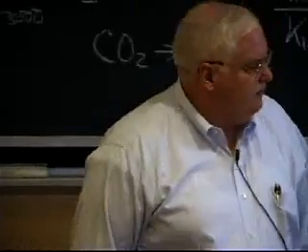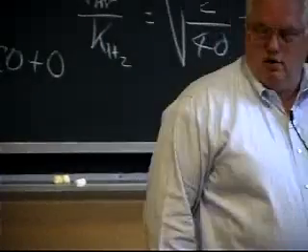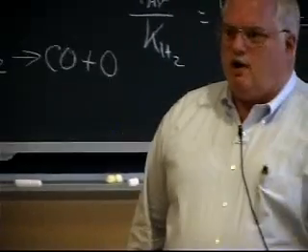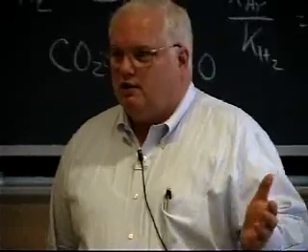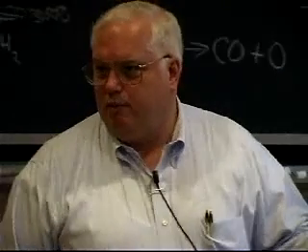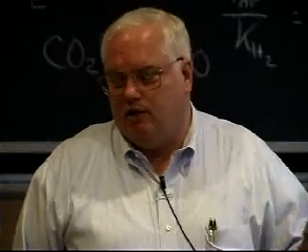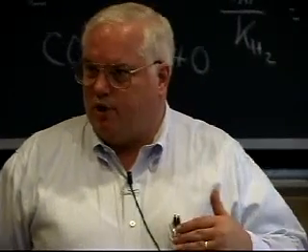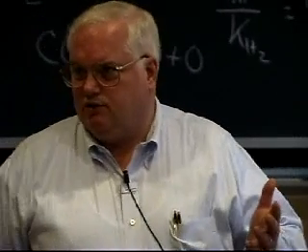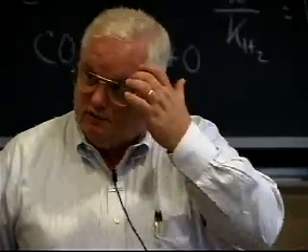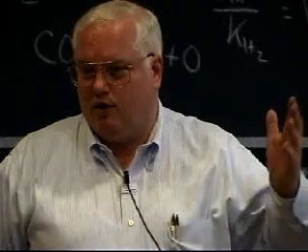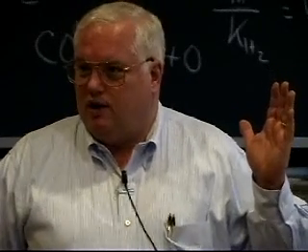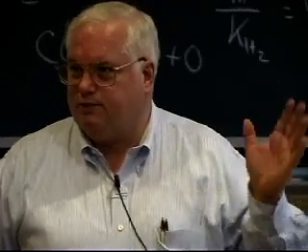Your total burdened cost to have a person welding and everything is probably more like $75 an hour. So yeah, you could knock $5 an hour off that or $7 an hour off that if you use 100% CO2, but the quality goes down. And then if you can't afford to spend an extra hour to clean all the spatter off.